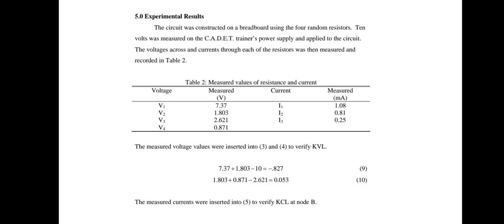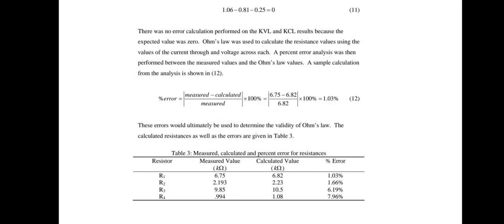And then there comes the supermesh concept, similar to the mesh concept, but a bit different. When a current source, dependent or independent, occurs between two meshes, we apply the supermesh concept to solve the circuit. We create a supermesh by excluding the current source and any elements connected in series with it, while taking KVL.